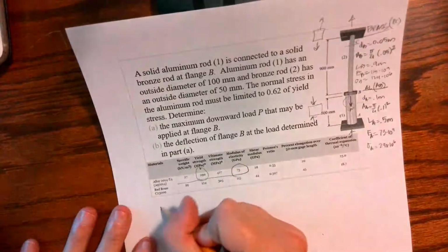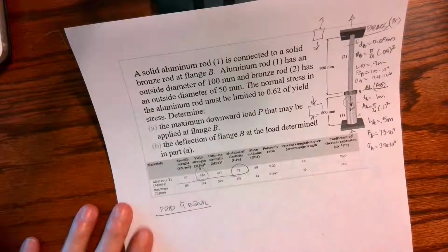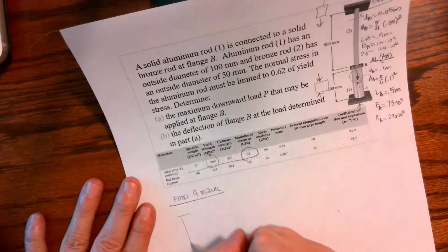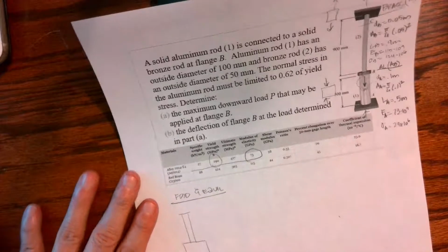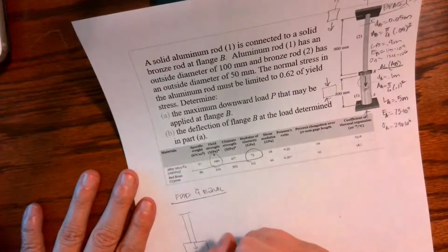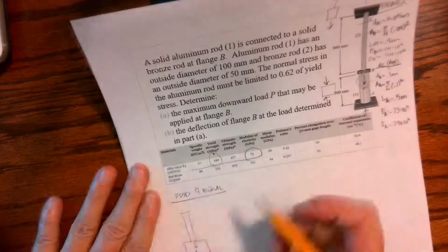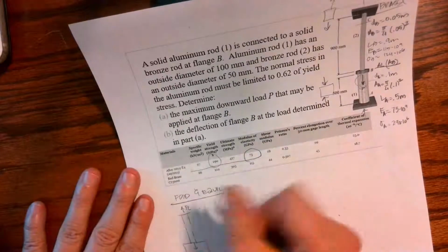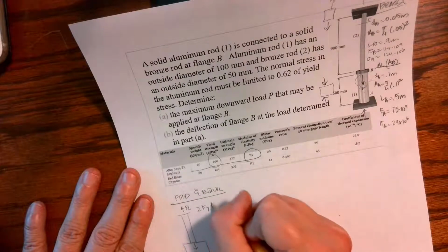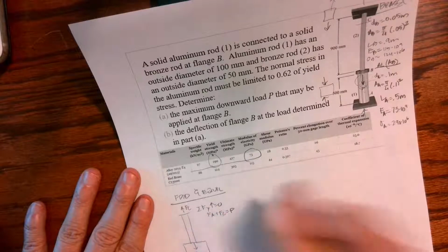We're going to start with a free body diagram and equilibrium, because we always start with statics, always, always. And I have my system here, not drawn to scale, and it looks pretty scary at this point. But I have a load P, and I'm going to end up with a force from A to B. Actually, we're going to call that force at A because it's my reaction. And I have a force at C. And so if I look at statics and I sum forces in the y direction equals 0, I know that FA plus FC has to equal P.